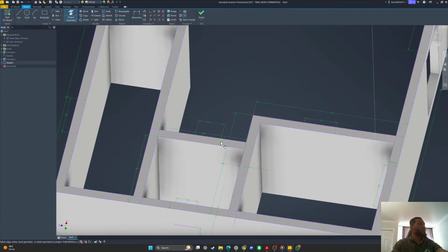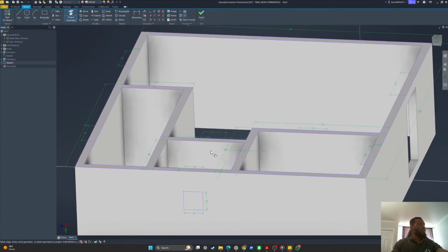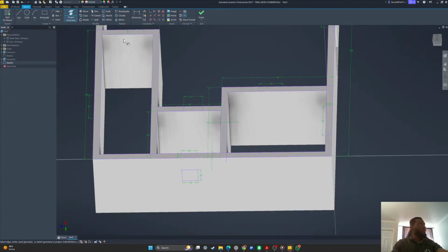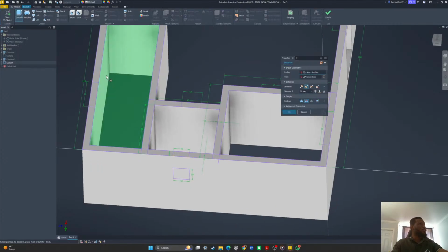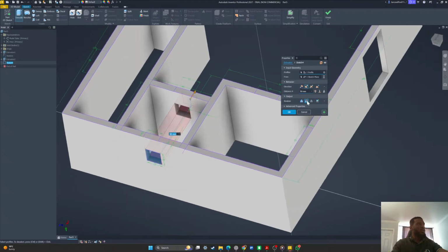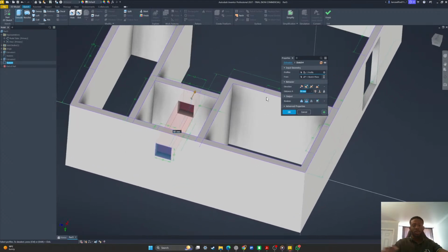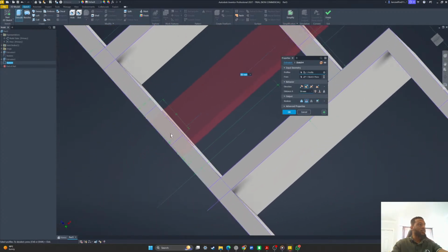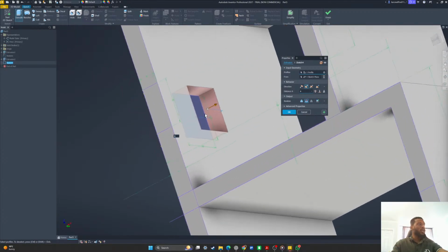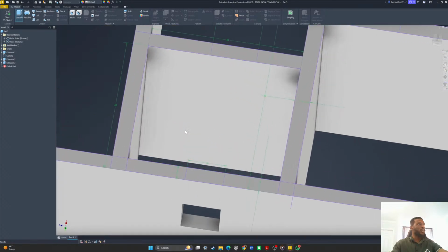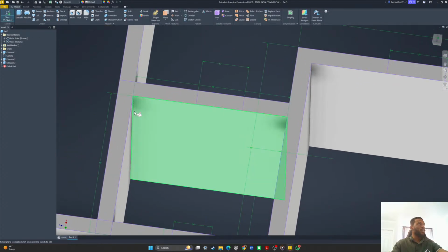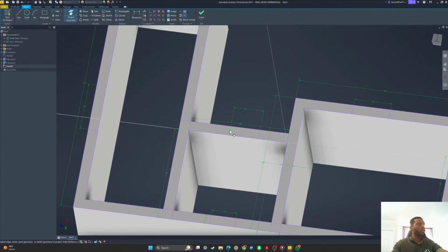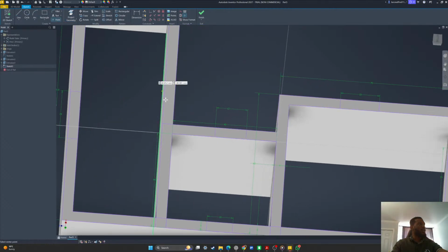I believe I should be able to select this next. I'll project this geometry to create this door. Then we'll click on extrude and cut like we did before. But this time we don't want it to go across this wall. So we're just going to make it cover the entire thickness of this wall, which was 4. And there we have it right there. Easy solution. So next we're going to make this door right here. So all we have to do is click on sketch again. And then like before, I want to project these 2 lines.